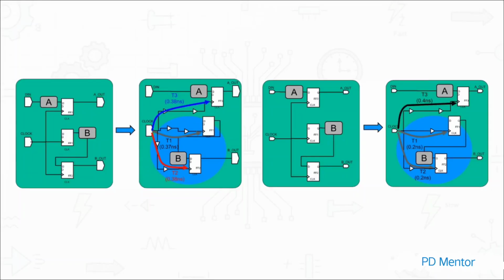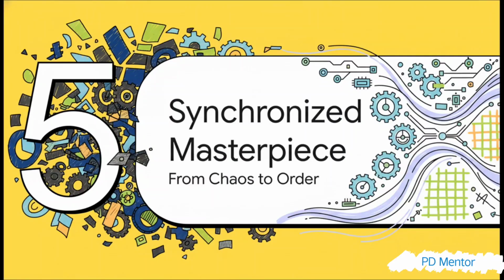Okay, check this out. This is a perfect example of what I mean. So on the left, using one approach, the clock hits component A at 0.3 nanoseconds and B at 0.38. Close, but not perfect. But look at the right. By focusing on just these two with a local skew strategy, the engineers nail it. The signal arrives at both A and B at the exact same time, 0.2 nanoseconds. Now, getting that kind of local precision can really boost performance, but it usually means the design process gets a lot more complicated.